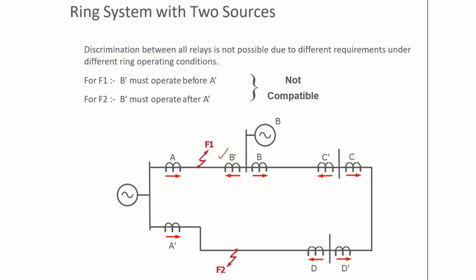If the magnitude of fault current changes, definitely your time of operation is going to change. That means the coordination will definitely be affected. These things we have already discussed in detail in our very first session on transmission line protection, that is why overcurrent protection is not used and why distance protection is used in transmission line protection. So that's why I'm not going into detail.